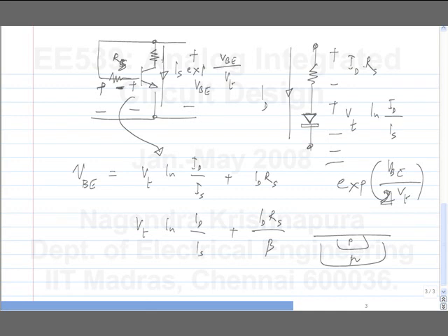I have read about this, but I have forgotten the physics behind it. I don't know why it doesn't happen in a bipolar transistor. So if you want to make a good diode, it's better to make a transistor and do this. When you have bipolar transistor technologies, you will use diodes for different things, and this is how you do it. You normally don't use just a junction of two semiconductor materials to get a diode. You will make a bipolar transistor and connect it up as a diode.